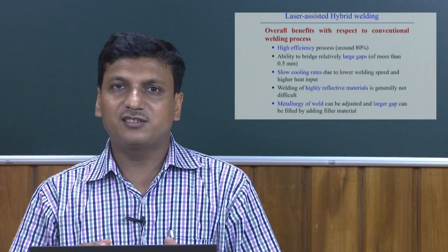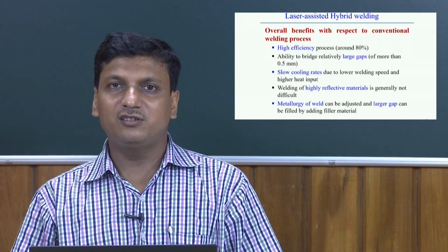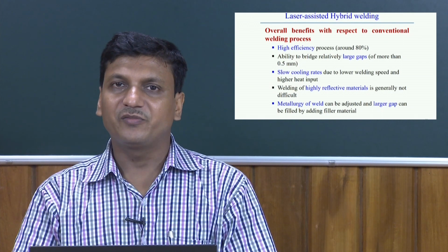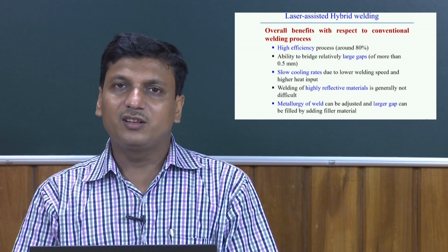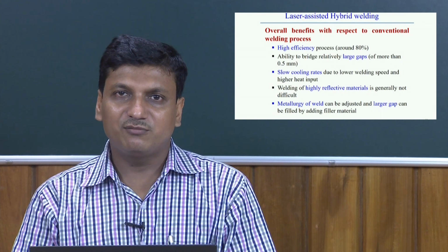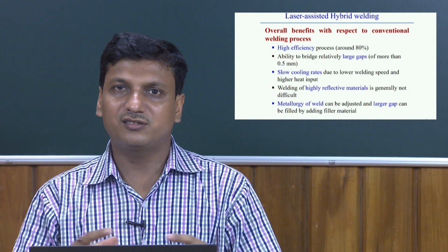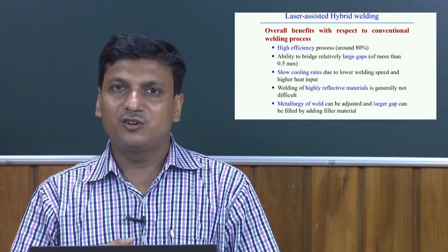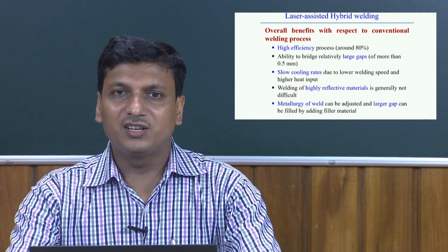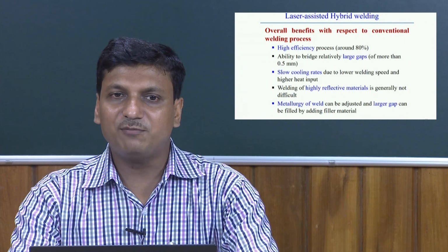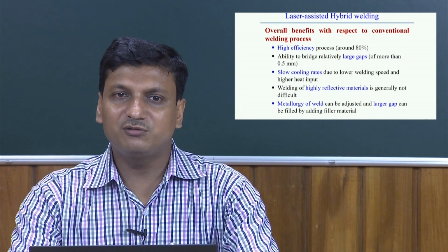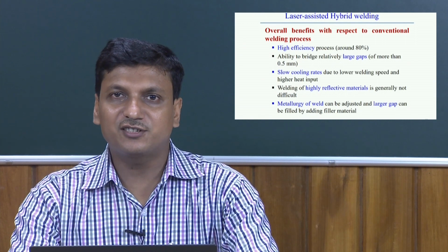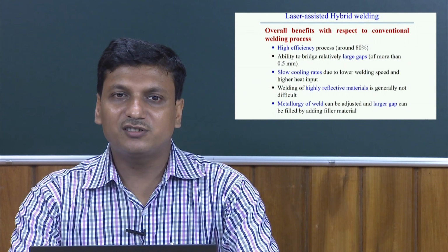Because in this case of the hybrid welding process, the volume of the weld pool is relatively more as compared to the laser welding process, because here the arc welding basically tries to increase the surface area of the fusion zone, and laser welding helps to create the large penetration. So, when there exists some large gap, probably it is advantageous to use laser assisted hybrid welding processes. And of course, very high thickness materials can be joined using these hybrid processes.